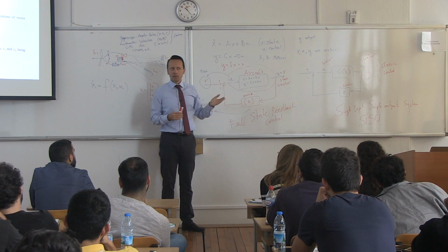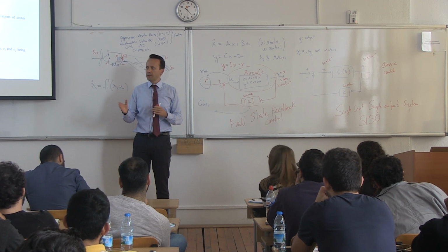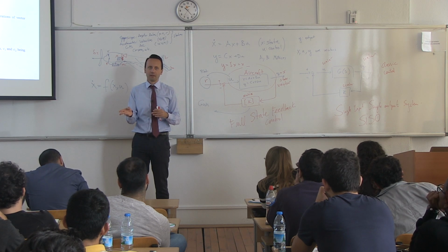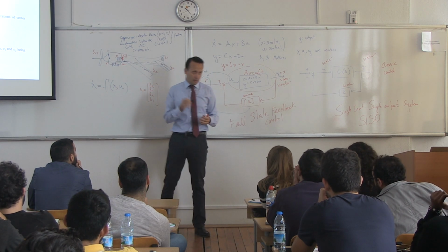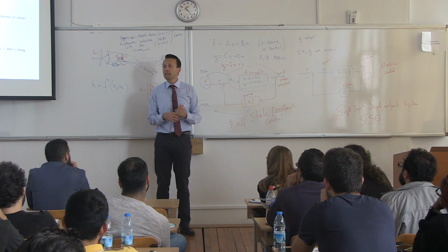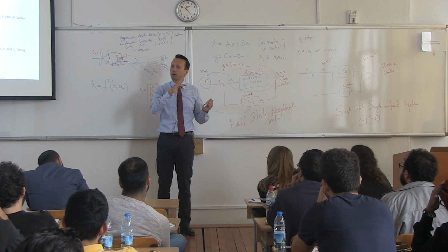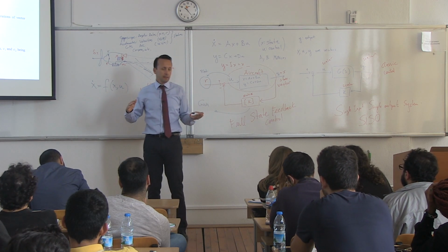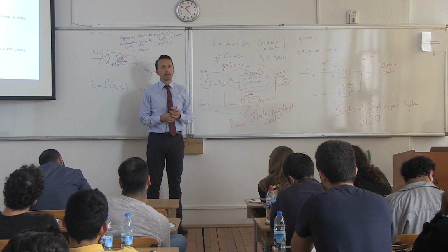Okay? Isn't that how you define sort of stability? We also talked about stability in flight mechanics. Stability is a property of an airplane or of the equilibrium points. Equilibrium points, of course, right? Stability is the property of the equilibrium point. An equilibrium point can be stable, unstable, right? And an airplane will have a lot of equilibrium points. A flight at 800 kilometers per hour is an equilibrium point. Maybe a flight at 600 kilometers per hour is another equilibrium point, right? So all these equilibrium points, there are many, there are infinitely many, in fact, equilibrium points, might have all different stability characteristics.